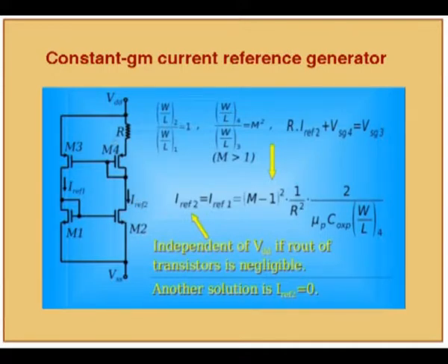So if I use this circuit with a small bias current, meaning I set IREF at a very small value, even this circuit will show a good output impedance. And that is desired, because nobody wants to design a reference current of, say, 1 milliamp. It unnecessarily dissipates current. Instead, I can design a reference current of 1 microamp and then mirror it. And when I am using a mirror, I can have amplification in the consequent stages.